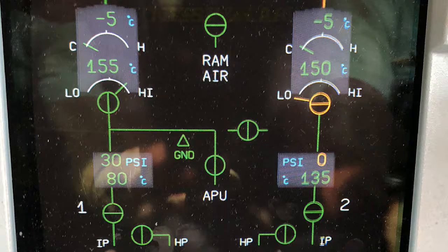The zone controller is located in the avionics compartment, and it controls the temperature for the cockpit and the cabin, and can be operated separately, as far as being able to manipulate and control the temperature in each of those zones. It also receives input from different temperature sensors, so I'll cover some of those. It receives those inputs, and then it sends an output to the pack controllers.